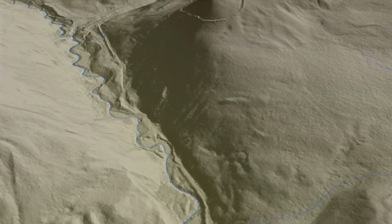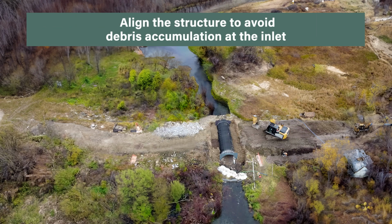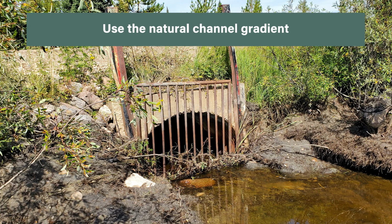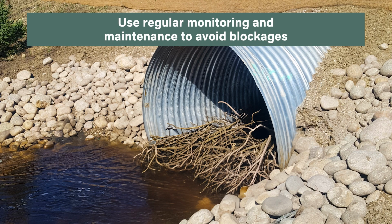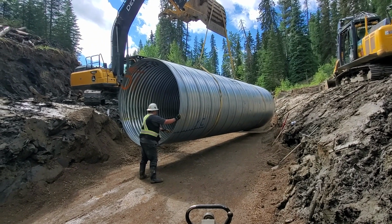General guidelines to keep in mind during the hydraulic design process include: align the structure with the upstream and downstream channel to avoid erosion and debris accumulation at the inlet. Use the natural channel gradient as the basis for sloping the watercourse crossing structure. Avoid design elements that could trap debris and plug the watercourse crossing structure, such as beaver guards. Use regular monitoring and maintenance as the best practice to avoid watercourse blockages at the watercourse crossing due to beavers or debris. There are also some specific considerations when culverts are chosen as the watercourse crossing